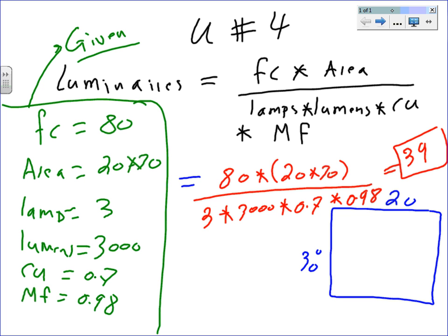So we're going to talk about distributing the fixtures in a room. Any question about calculating the foot candle before I move on? I can't emphasize enough that the next step is very important, because that's what you are going to be doing in Visual: first, finding how many fixtures, second, how you place them. Third, we're going to show you how Visual is much easier than that. There's a trick where the software can do all this calculation, even the layout.